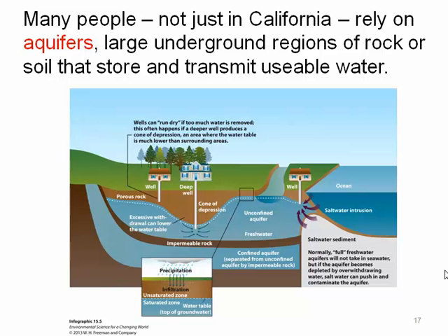That can affect domestic wells, agricultural wells, and essentially eliminate a supply if it becomes contaminated with salt water. So groundwater management, although useful as a supplement and as an expansion of water resources where water can be stored and then taken at need, is also prone to management issues as far as maintaining its long-term viability.